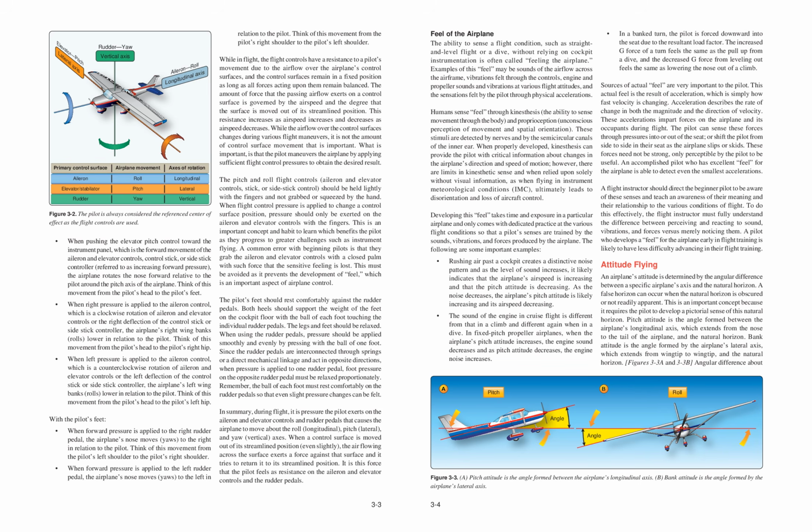The pilot can sense these forces through pressures into or out of the seat, or shifts of the pilot from side to side in their seat as the airplane slips or skids. These forces need not be strong, only perceptible by the pilot to be useful. An accomplished pilot who has excellent feel for the airplane is able to detect even the smallest accelerations.